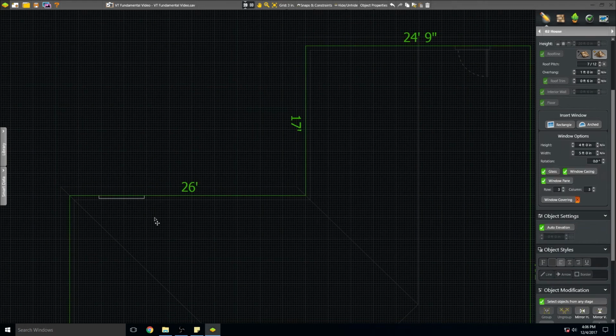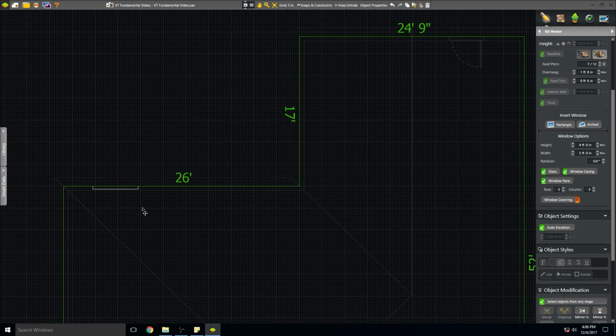Left click on your window to select it. You should have your move tool by default, so you should be ready to just left click on that and select it. See the little crosshairs symbol on your cursor? That's the move tool. It's kind of your home tool. When you're not drawing, you should be seeing the move tool. So with your window selected, I'm going to have you press Control C. Nothing is going to happen because that shape just went into memory in the system. Now I'm going to press Control V as in Victor, and that's going to produce the copy of the window.